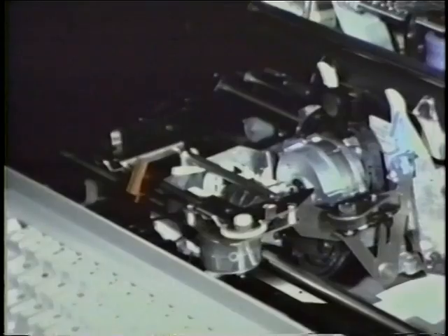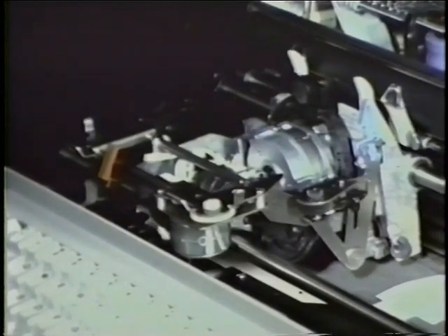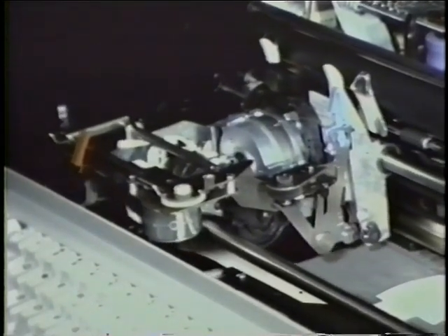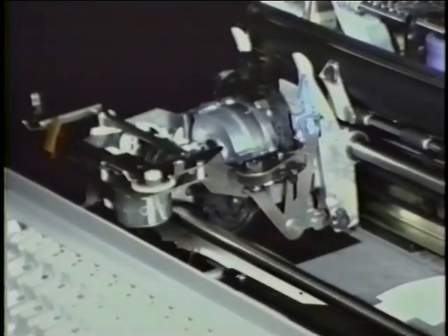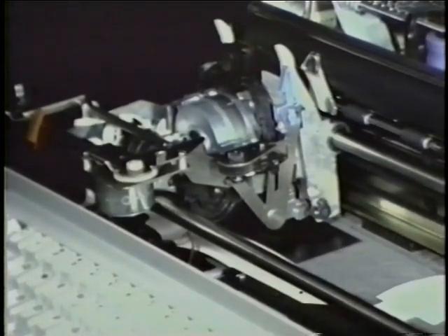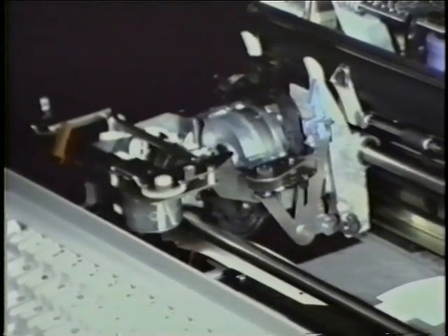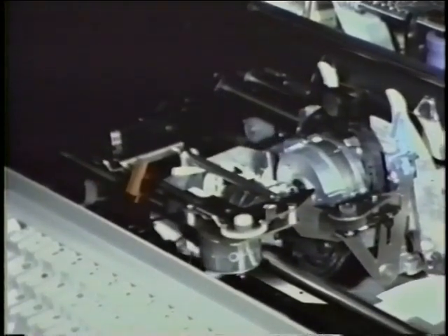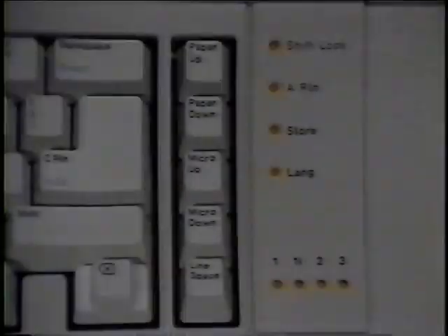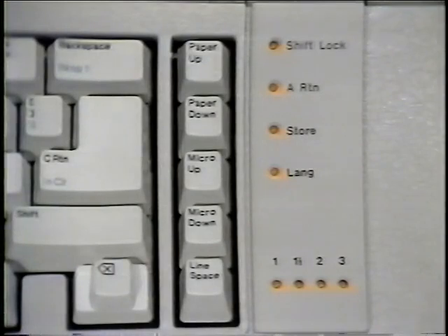Next, the transport motor drives the carrier to the left side frame to check the transport motor for an overcurrent condition. Then the platen moves down slightly and back up. This checks the paper feed motor. Then the print hammer fires lightly once to check the hammer solenoid as the carrier moves out to the left margin. Finally, all the indicator panel lights turn off except for the single space light.